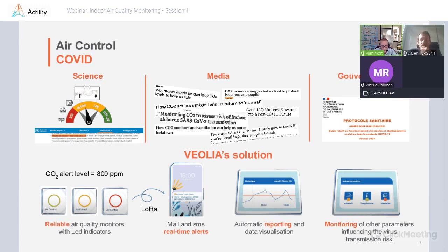Yeah, okay, that's right. Now for some species like NOx and ozone, we have what we call MOX sensors, metal oxide sensors, which are now so small that the energy consumption allows them to almost work on batteries. But it is, of course, pulsed; it's not powered all the time. And the lifespan is over 10 years, compared with the electrochemical sensor, where the chemical compound was drying over time and the lifespan was a few years, even sometimes 1 year. So 10 years is a good base for such sensors, which is the same for CO2 and the same for particles. This is quite consistent, even if some sensors surpass 15 years of lifespan.